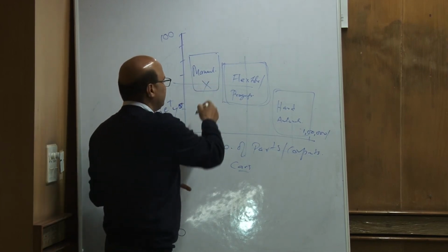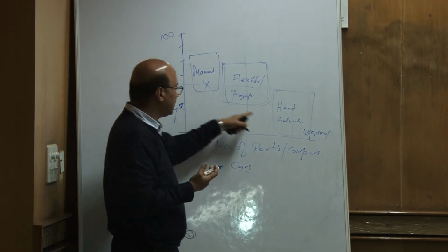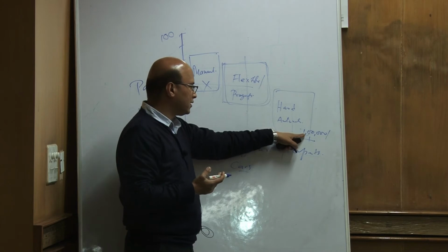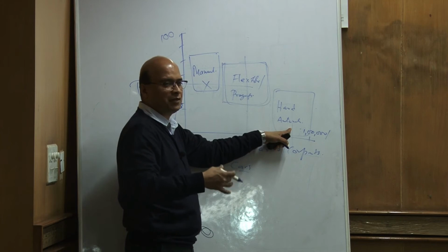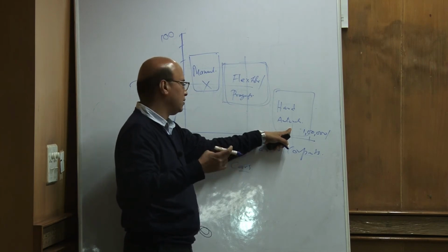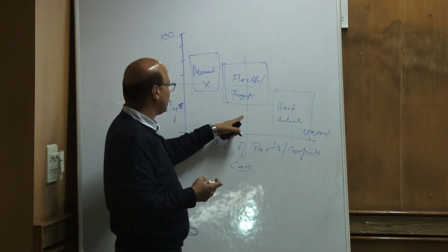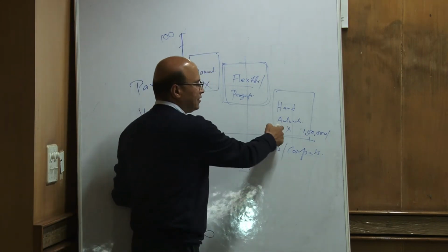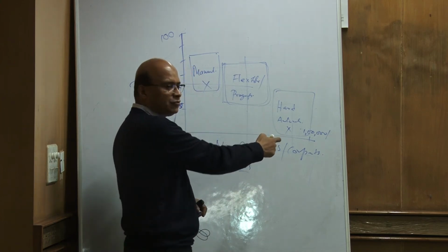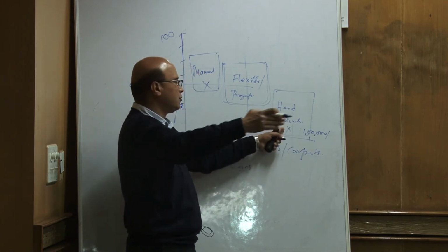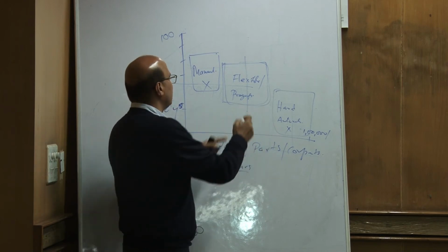Robots cannot be used economically here. On the other side, the large number of parts are there, so hard automation is much easier here. Something like transfer lines, pick and place, just your normal hard automation devices. Here also robots are not used except for things like spot welding, spray painting. Otherwise, it is not economical again. So simply, if a part has to move from one place to another, what they'll be using is indexing or simply transfer devices, but not robots. So robots are only available here.